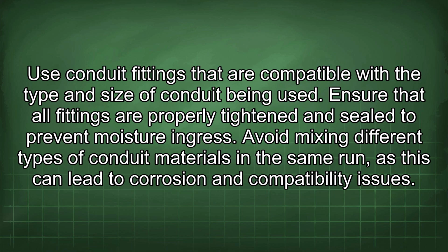Use conduit fittings that are compatible with the type and size of conduit being used. Ensure that all fittings are properly tightened and sealed to prevent moisture ingress. Avoid mixing different types of conduit materials in the same run, as this can lead to corrosion and compatibility issues.